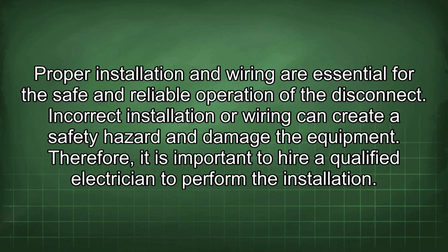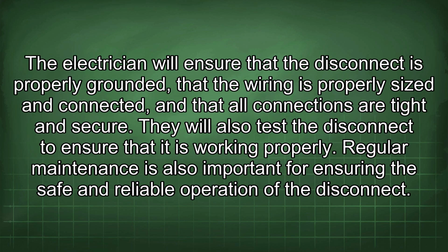Incorrect installation or wiring can create a safety hazard and damage the equipment. Therefore, it is important to hire a qualified electrician to perform the installation. The electrician will ensure that the disconnect is properly grounded, that the wiring is properly sized and connected, and that all connections are tight and secure. They will also test the disconnect to ensure that it is working properly.